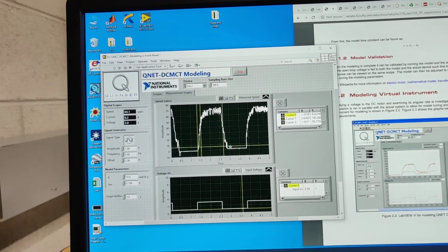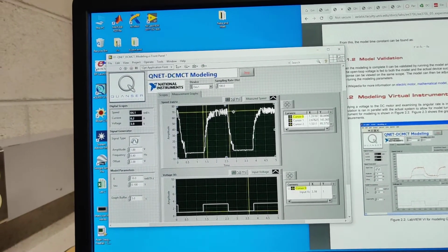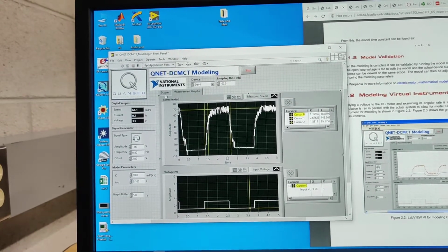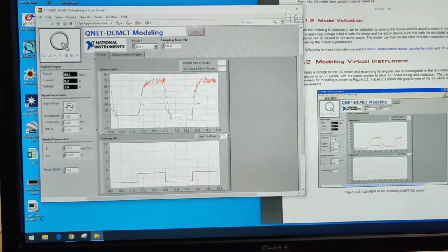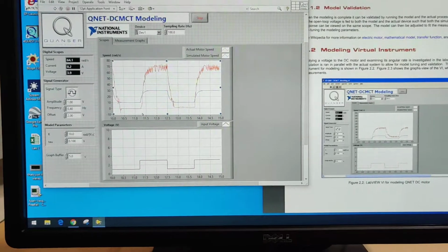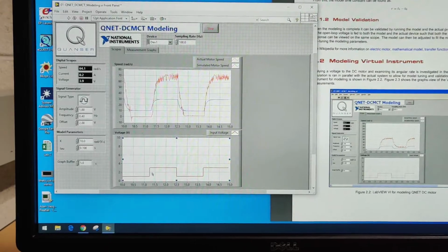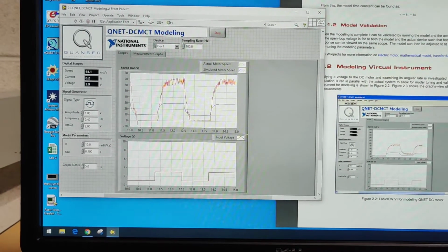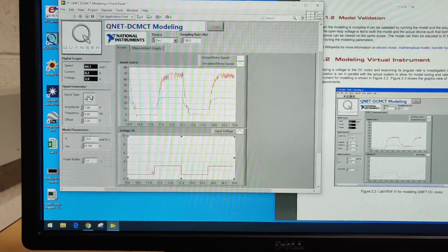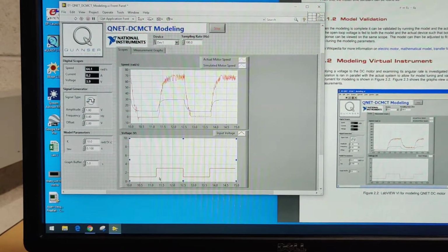If we go down, it's about 0. So we can do the calculations with the subtraction to get the delta Y, and similar for delta U as well. But we can also use eye observation to give some approximate number. Since the amplitude is 1 amp, it's positive 1 and negative 1 surrounding both sides of this offset 2. The 2 is the average value, and positive 1 makes it 3, and negative 1 makes it 1.